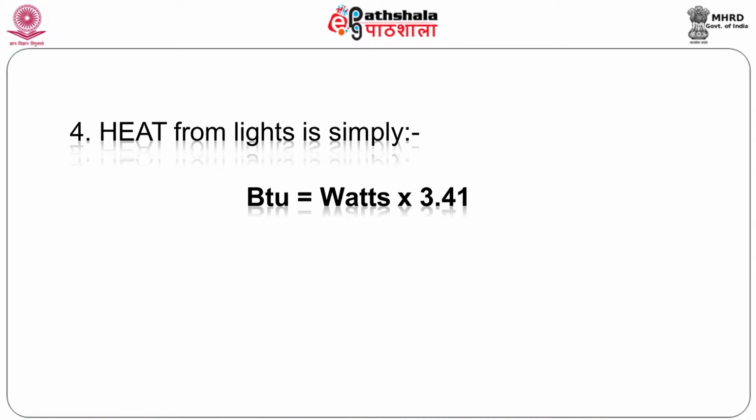The next source of heat is from fresh air. This again is something that is imposed upon you for a requirement of personal usage. You require a personal indoor air quality, and you need to maintain a certain amount of oxygen level. A certain amount of fresh air is required. The fresh air that you bring in from outside obviously is from the ambient. It is at 40 degrees. It has a wet bulb associated with it of 28 degrees centigrade. Now, that hot humid air, when it comes inside as a requirement for health, obviously becomes a heat load to the air conditioning man. Now, these three factors put together are all that is required from the external sources.